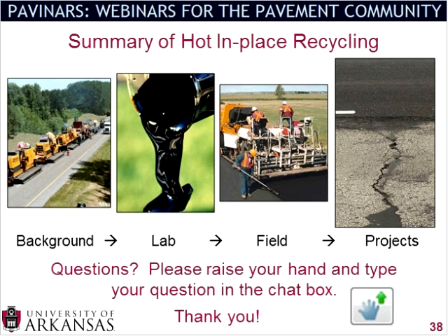And that's an excellent question. You saw a couple slides ago I said that although it is not required, some states opt to have a surface course. And I really think that that's up to the agency or the owner as to what they want to do. For example, if this area has had historical friction problems, you might want to put a chip seal on top of there if that's able to be done. If you want to add a little bit of structural capacity, you would want to put maybe a 2-inch overlay on there or something that could help out with that.